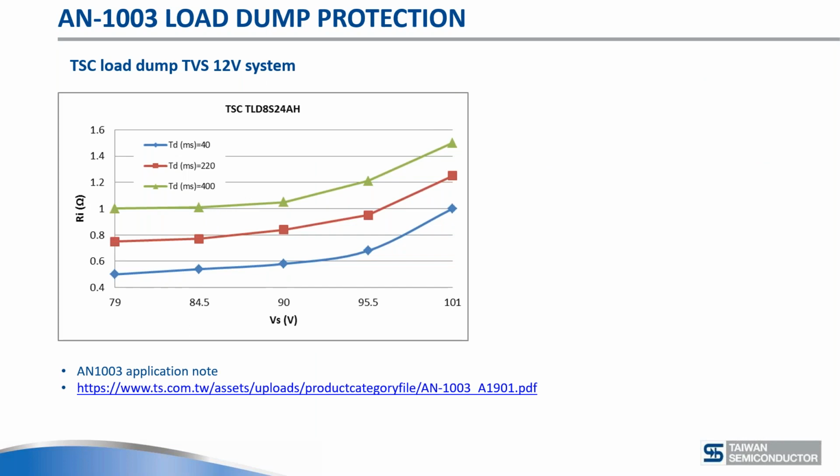This helps you, and this is just one graph from it, and I'll briefly explain it. We have all the 3 load dumps characterized also for different conditions. So if you have a load dump, let's say the 19 volt load dump, which lasts 40 milliseconds, then at least you have to have around 0.6 ohm in series with the load dump, a series resistance, for it to work.